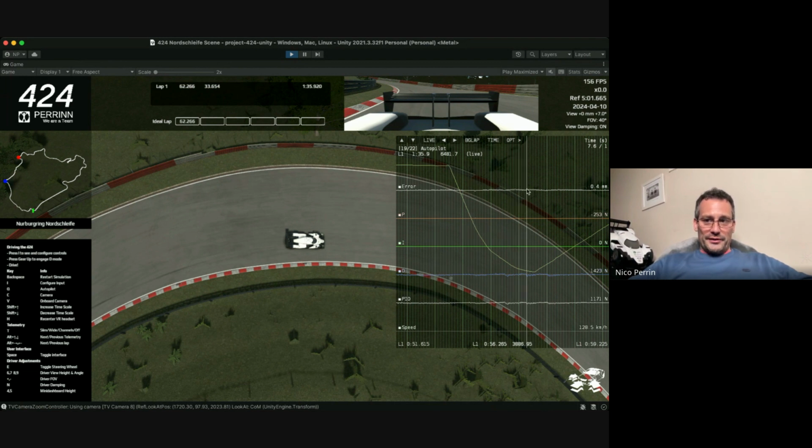The error in white is the distance between the current trajectory and lateral distance to where we want to be. We want to put the car back to where it was. So we're applying a force with a PID system, and this force is in Newton here, and it keeps the car always maximum 1 millimeter from the trajectory.